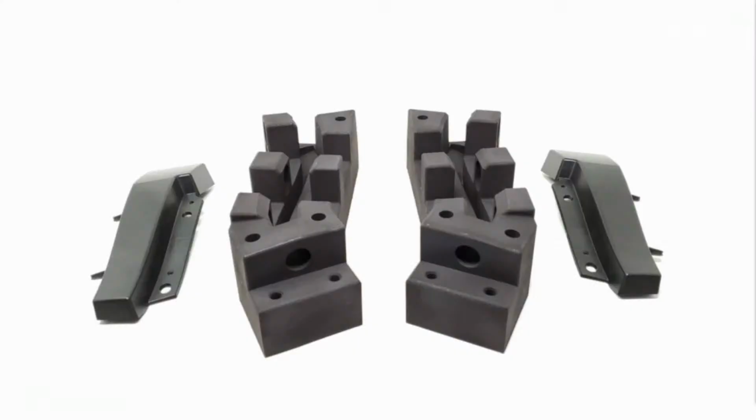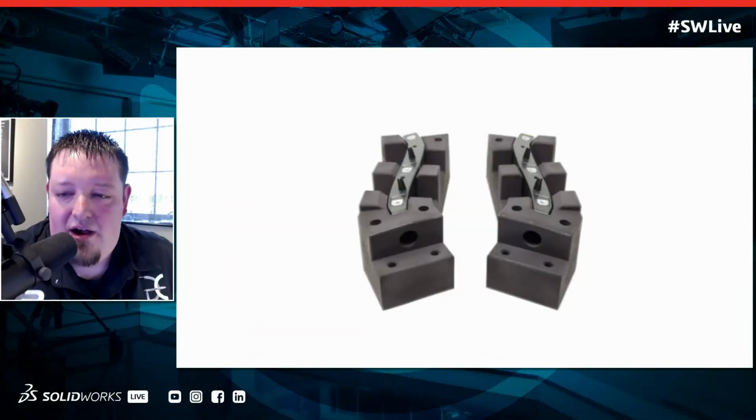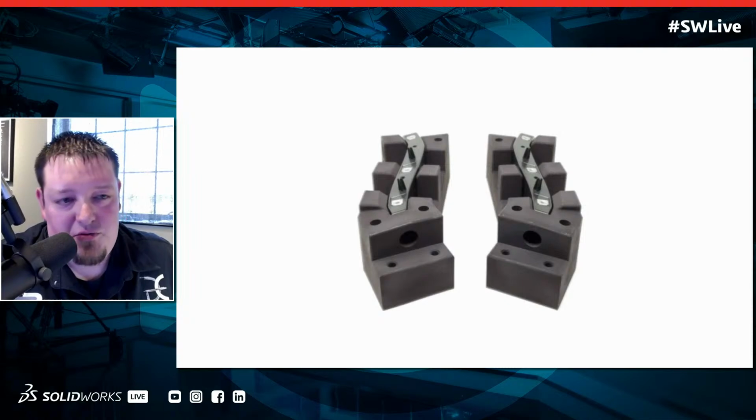Talk a little bit. So this is a part you designed for MJF. I can tell by looking at it, it's a bit of a fixture. Maybe explain what the part does here. Yeah, so this is an assembly fixture. This gets bolted into a machine, and then there's a left hand and a right hand, so they'd be sitting on the machine pretty much like how you see them right here. And then you can see how the customer, the end part, the part that's actually being manufactured here, gets loaded inside of it. And what happens is a swing clamp comes down and pneumatically locks these into position, and there's an operator sitting there putting these metal clips in.